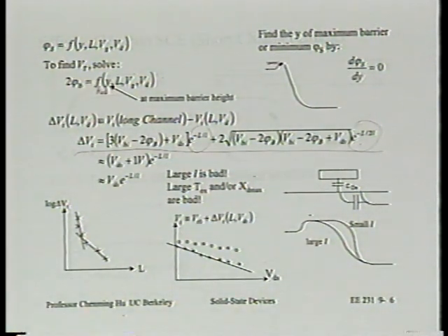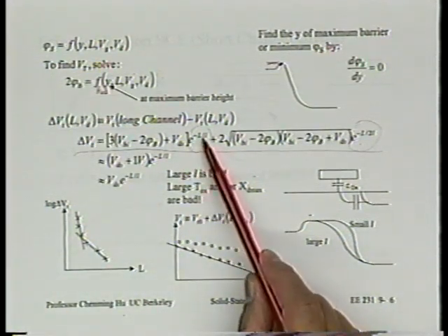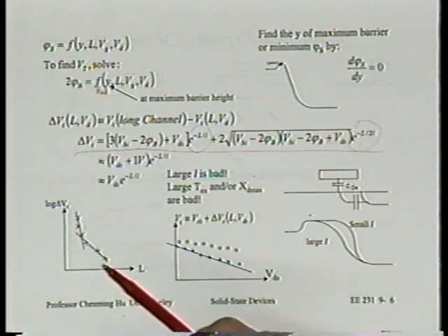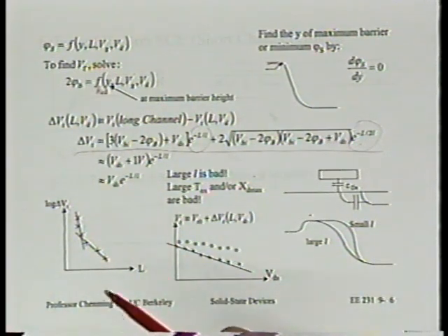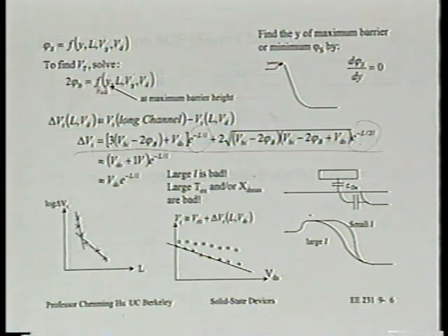But we just found out a few months ago, in the new version of BSIM3, BSIM4, because BSIM4 uses a compact model for circuit simulation, we actually went back from exponential function to hyperbolic functions of L, because the users find out using that fits the Vt data even better.